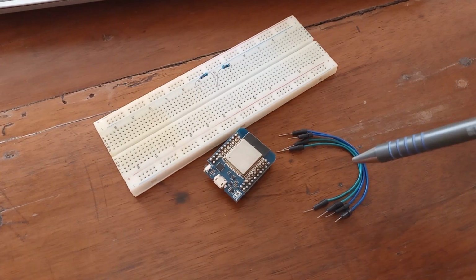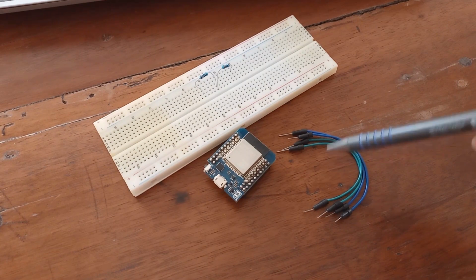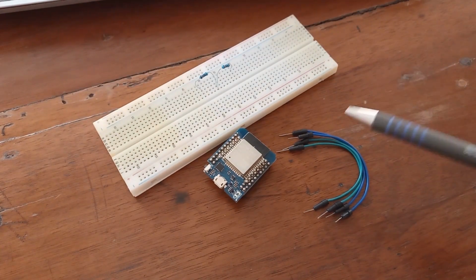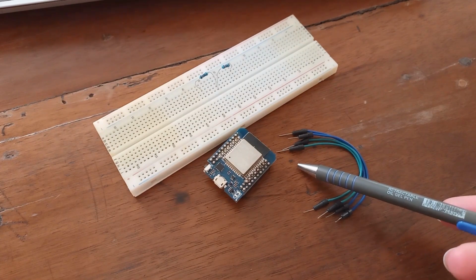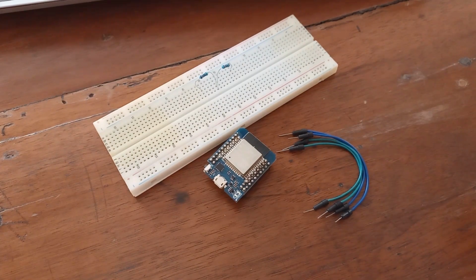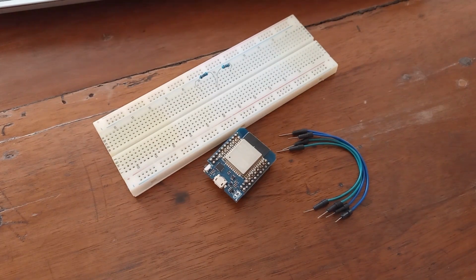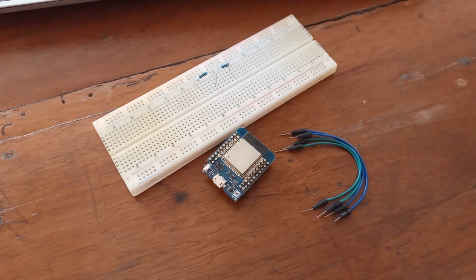And now, why do we need these jumping wires and these 2 10K resistors? Because electronics of our microcontroller, it's extremely sensitive and you can easily find some leftover charge that is going to mess your readings. For that reason, we are going to use these resistors to pull our signal down. And don't worry, in this episode I'm going to show you exactly how to do that. And now just connect your microcontroller to your computer and we are going to start coding.